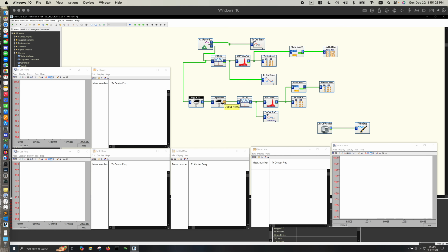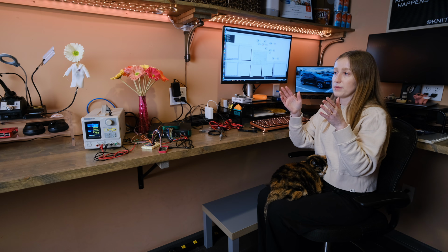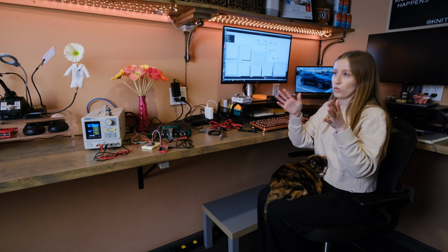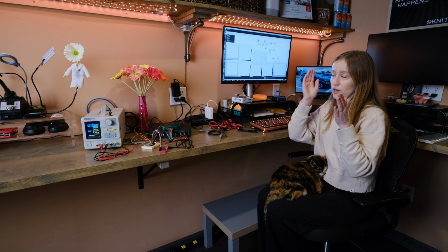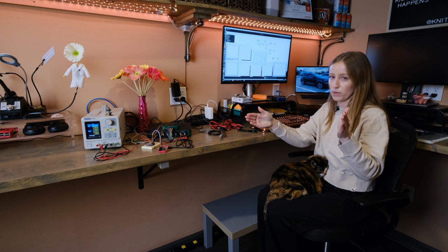Then I put it through a second filter, a high pass filter with a cutoff frequency, before it starts allowing frequencies through, of 500 kilohertz. So that gave me a bandpass filter with a 1 megahertz range around my center point of 1 megahertz. So 500 kilohertz to 1.5 megahertz.